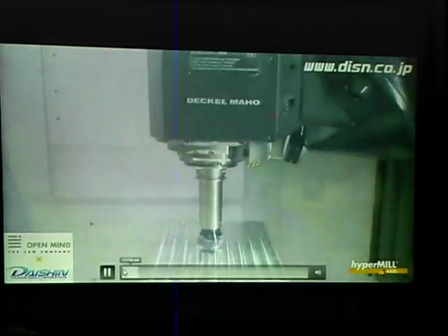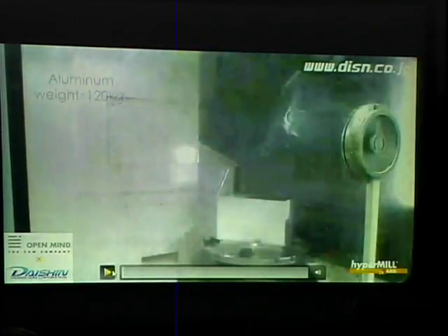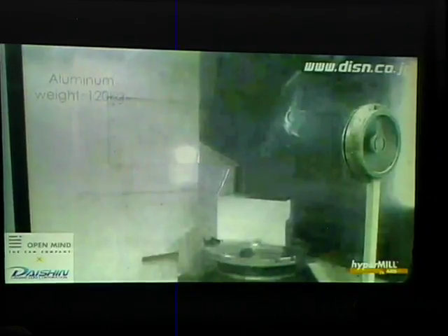Back before probing routines existed, and wow, that sounds horrible, you would manually locate, say, a corner or a measurement point on the machine, and give the machine that point and say, this is the starting point. This is your zero, the origin of your coordinate system, and all of your coordinates in the G-code are built to work from there. And you can give it specific commands to take care of that.